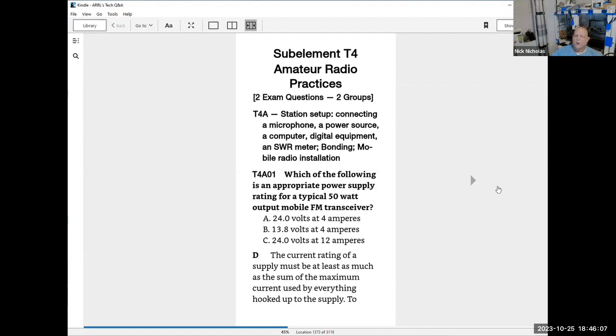I'll correct it if I'm wrong. It doesn't matter. All amateur amplifiers and the finals in your radios are only about 50% efficient. So if they can output 50 watts, they need 50 watts more coming in. So our calculation was for 50 watts, and we need 2 amperes. But in fact, you're going to need 4 amperes.